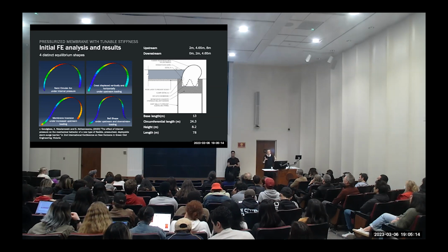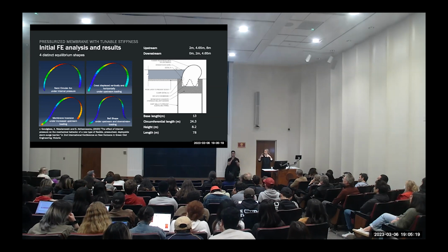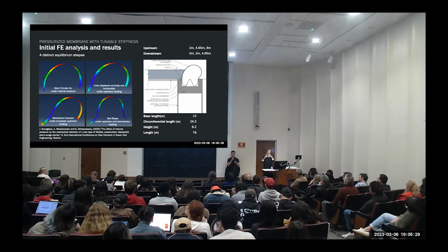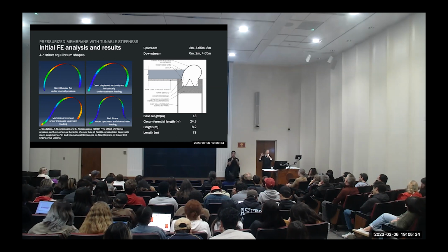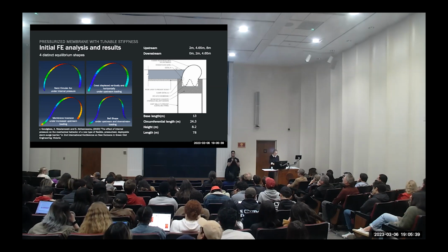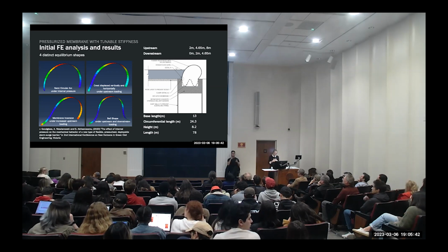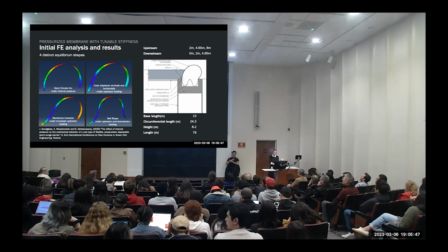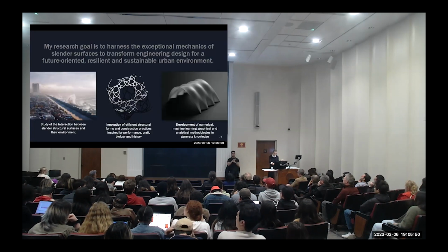And so again, the same thing as what we found with the nets is that you can actually control the stiffness of this balloon, so how much it is going to deform with the pressure that you're putting on it. So the loading that you put on it, in this case the pressure, you can actually make this balloon stiffer. It's just like blowing into a balloon, right? If you blow a lot in it, it will become quite stiff. If you leave a lot of air out, the pressure is very low, it becomes very flexible. And so this can also be used for these very large scale storm surge barriers. And so we have kind of proven that these barriers are feasible at that scale.